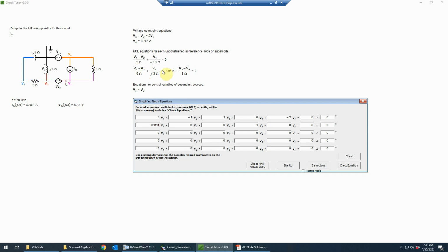Okay, and then for the imaginary part, remember that 1 over j is equivalent to negative j, because j squared, by definition, is negative 1. So therefore, the reciprocal of j is always just negative j. And remember that we also have to take the reciprocal of the 3, because both the j and the 3 are in the denominator. Sometimes people just want to bring the 3 upstairs, but of course that doesn't work because it's in the denominator, not the numerator. So this would be minus j, 0.33. And I'll enter that to 4 digits, so it's a repeating, of course, decimal there for 1/3.